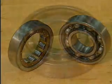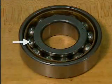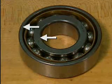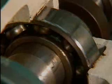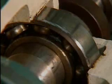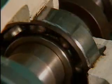The rolling elements in a rolling contact bearing are either balls or rollers made of specially hardened steel. In this example, the rolling elements are balls, and they are set between two hardened steel rings, an inner ring and an outer ring. These rings are often called races. In a typical installation, the outer ring is fixed and doesn't move. The inner ring is fitted to the shaft. As the shaft rotates, the inner ring also rotates.